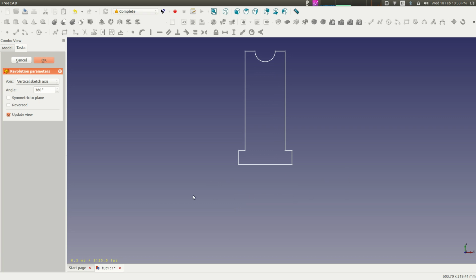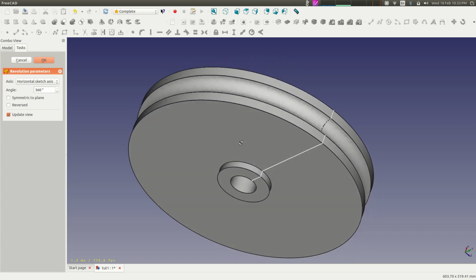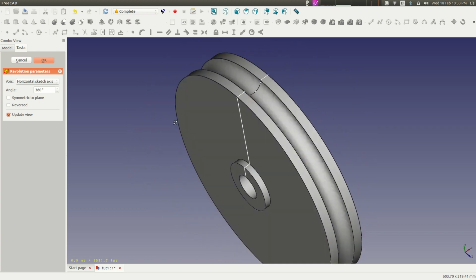That's why you notice that we've only drawn one side of it. The axis is down here essentially, and we're going to revolve it around that axis. But you notice that I didn't draw another one down here, because it would revolve the one through the other, and that would just mess everything up. That's why with the vertical axis, right now it's trying to revolve it about this axis. And as you can see, there's an object on each side, and that technically revolves through itself, and that's not allowed. As you can see, no revolve has occurred. There's nothing there. If we click the other axis, the horizontal, you'll see that it likes it. That's okay, and it does it. It draws it for us, so renders it.